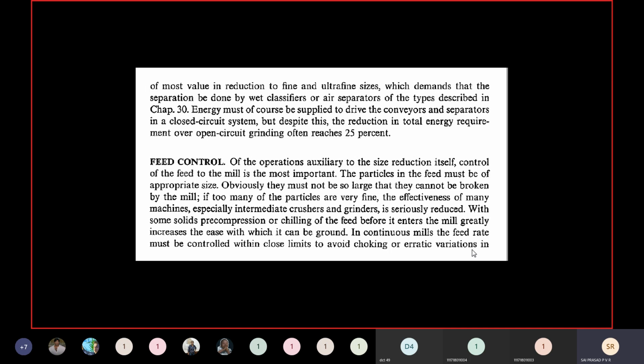No problem. But suppose, vice versa, you are not feeding the solid particles steadily, or you are putting in all the solid particles at a stretch. Then of course it is called choking. Because of the choking, the machine has to do heavy duty to crush those jammed or choked solid particles, and thus suddenly it takes more current. Nowadays we have MCBs. Whenever the current drawn through the system increases, it automatically stops the machine.